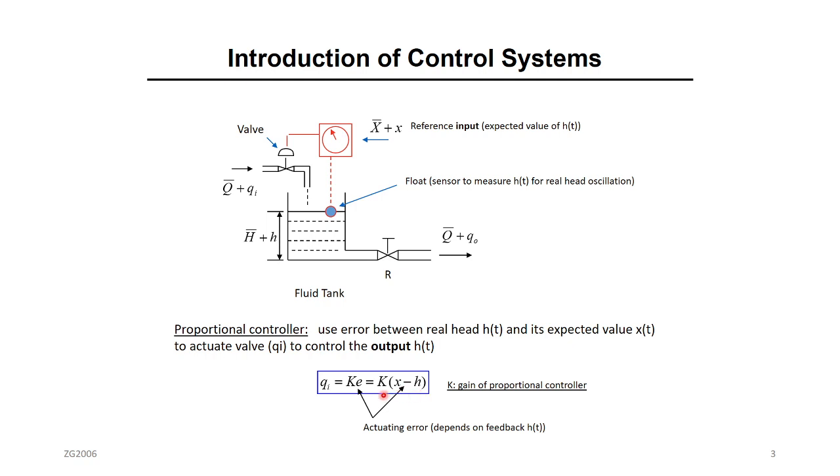Now you always need to pick one stable, constant value for K. For example, I will design K to be 1, only 1. So after a while, you measure it, it's 0.5 H. 1 minus 0.5 is 0.5 times K, which is 1. It is 0.5. So QI will be 0.5. What does 0.5 mean? It will pour more fluid, like 0.5, into the tank.